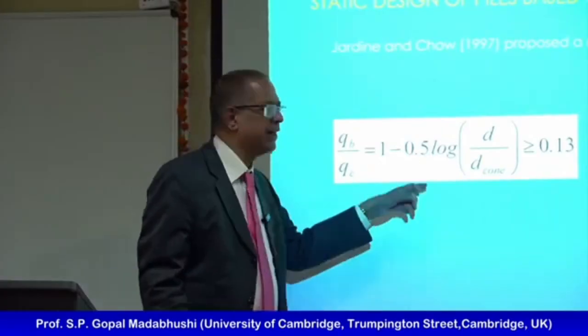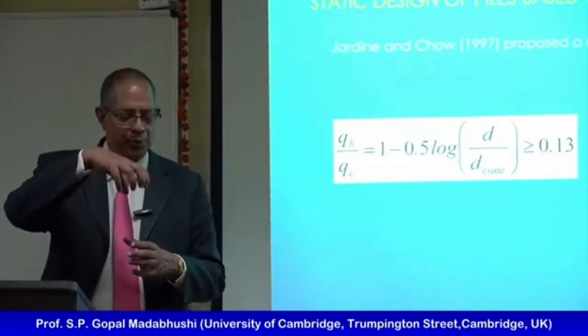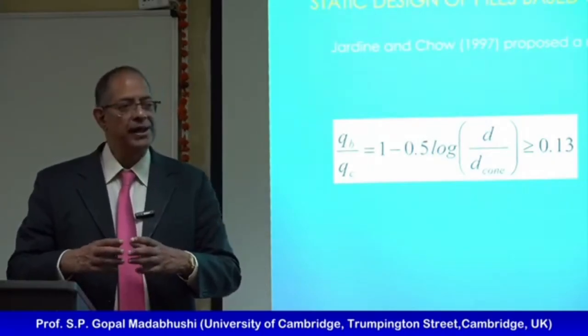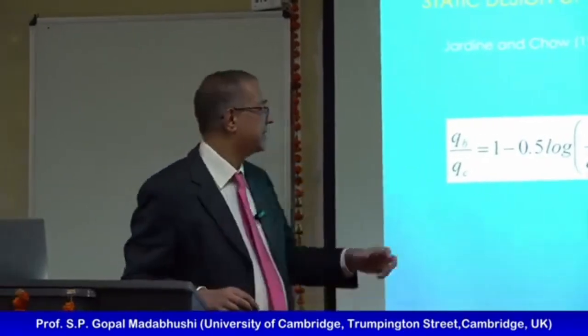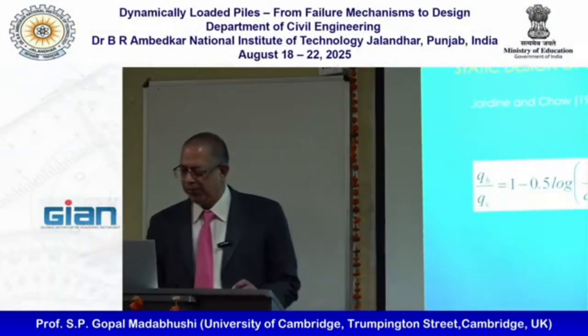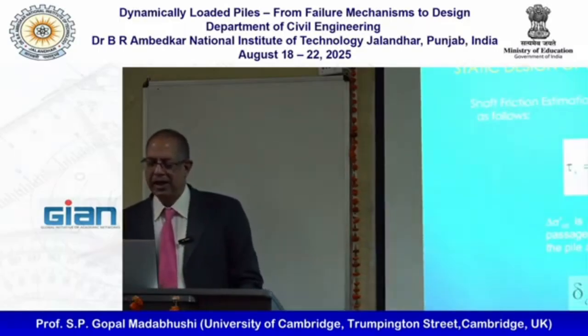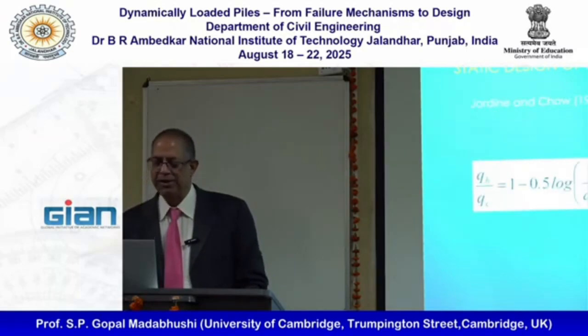And here what they're assuming internally is that as I'm pushing my pile or the cone in, the soil around is undergoing cavity expansion, and that expansion ratio is like a Ln function or a logarithmic function. Randolph later on has come up with, that is the earliest one.